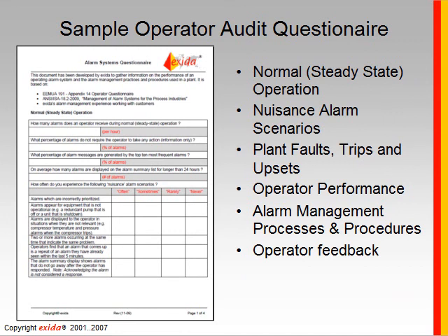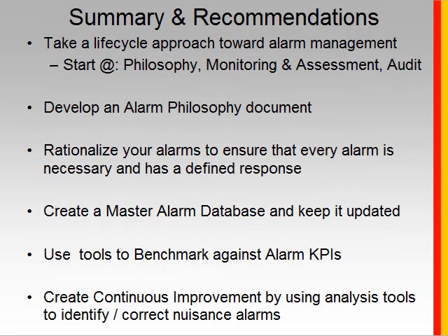Here's an example of one of the tools that might be used during an audit. This is an operator audit questionnaire that we've developed here at Exida to help understand the alarm system performance during normal, steady state, nuisance alarms, etc., and operator performance. This is very good to use in addition to the monitoring and assessment, because the direct feedback from the operator is very significant in determining what needs to be changed to optimize the alarm system, so it really works for the operator.